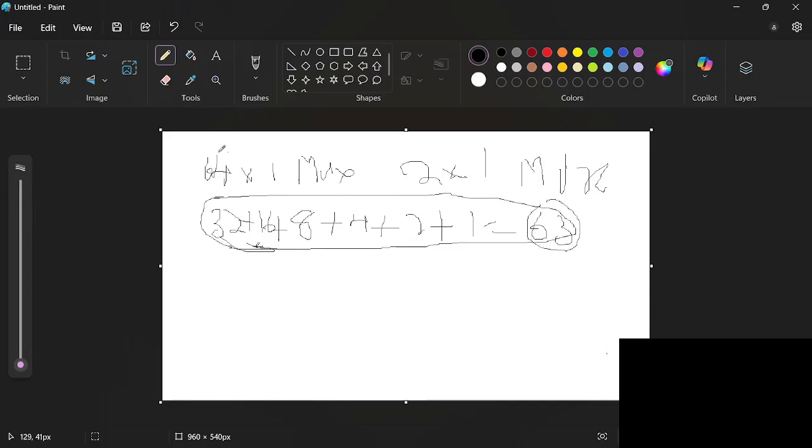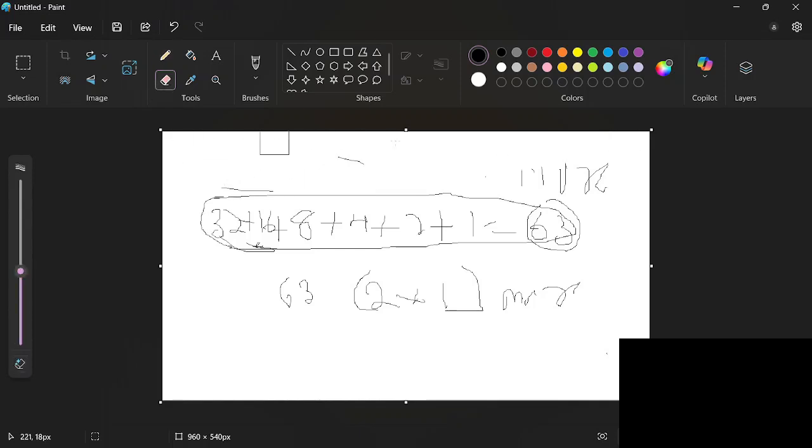If you exclude it because you think it's too big, you might get in trouble. So the addition of the outcomes was 63. So basically you use 63 2 by 1 mux in order to form this 64 by 1 mux. You get me? So now with this concept,